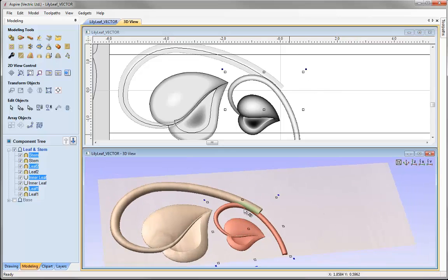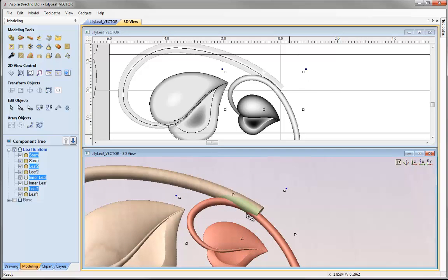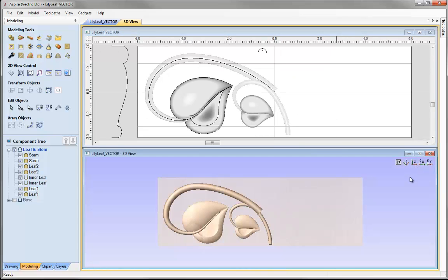And if we look at the 3D view, we can see that's coming right in there, so I'm happy with that. Then we'll just press F to fit that to screen, look at that down Z, and then ultimately what we want to do is create a mirrored copy of these two components on the other side. So I need to look at removing this smaller stem area here, as I don't need that.